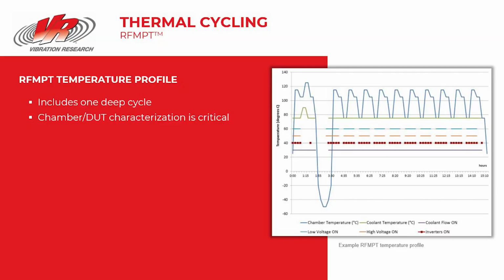The RFMPT thermal cycle is intended to expose the test parts to one cycle of peak hot and cold per vibration step stress cycle. In addition, thermal cycles with smaller delta T's are used for the duration of the vibration testing to accumulate as much thermal damage as possible. It is important to understand how the number of thermal cycles corresponds to accumulated end-use environment thermal exposure so that an understanding of field reliability can be gleaned and reliability growth can be tracked.